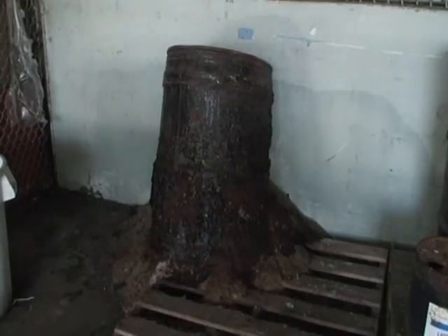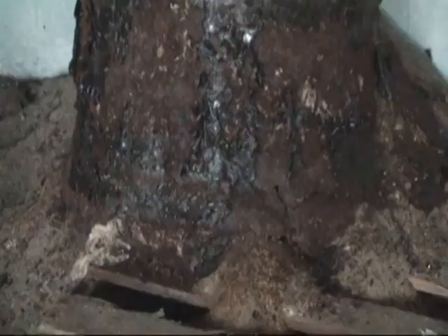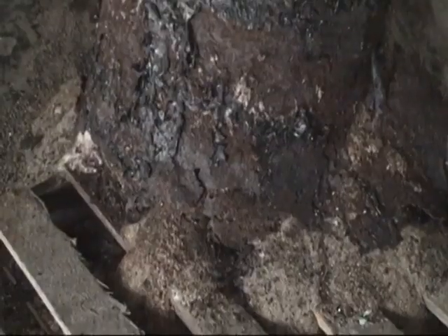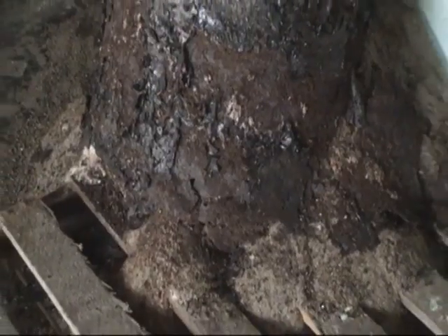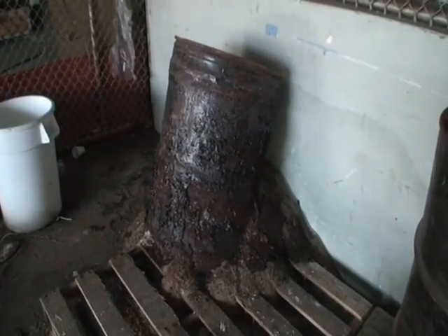If you ever encounter a drum of any kind of unknown in this condition or not, and it's not labeled, and you're not experienced and you're not an emergency responder, do not do anything on your own to try and figure out what's in it. Don't take the bung off of it. Don't sniff vapors coming out of it. Don't stick your finger in it, and don't kick it. Your worst case scenario is that it will be some kind of an unstable material.